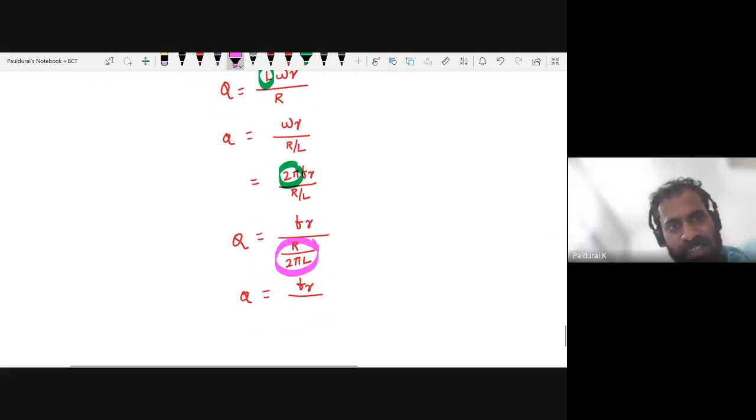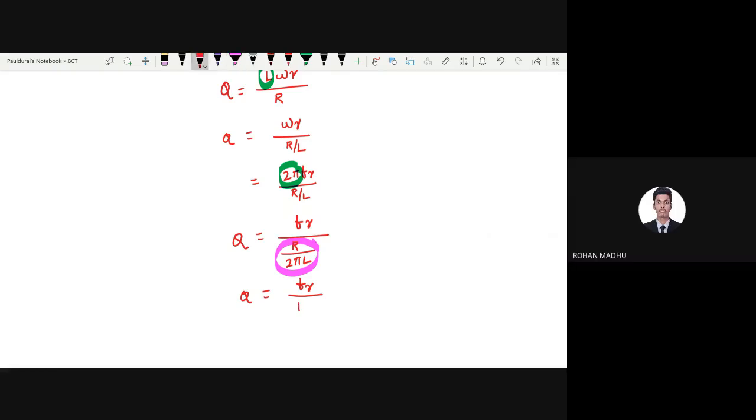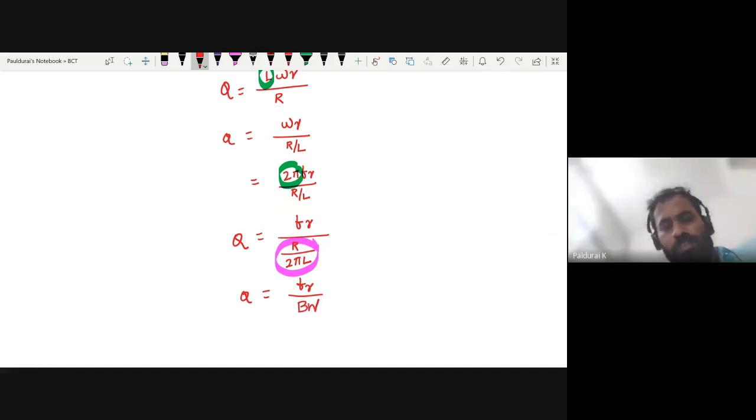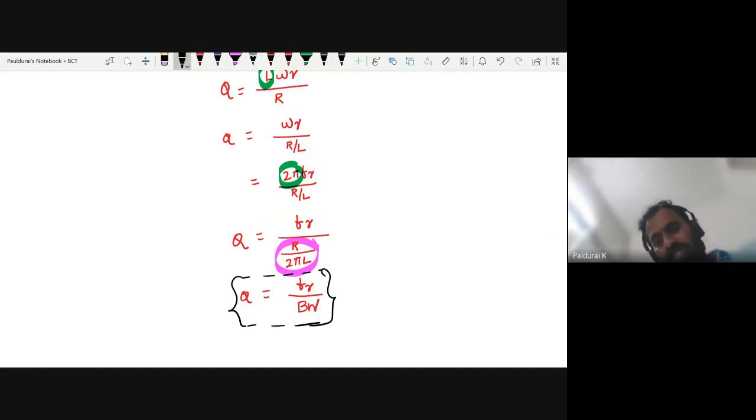Who is this guy? Bandwidth. So it's another important relation. Quality factor and bandwidth are inversely proportional to each other, so quality factor is equal to resonant frequency divided by bandwidth.